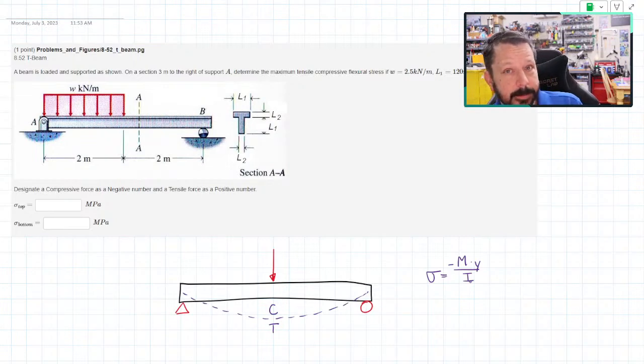Just like technically you could choose left or right to be positive for the summation of forces in the x-axis, or which way is up for the y-axis. In here, so that we all draw the same shear and bending diagrams, we have to have a certain direction for these moments to be positive and a certain direction for them to be negative.